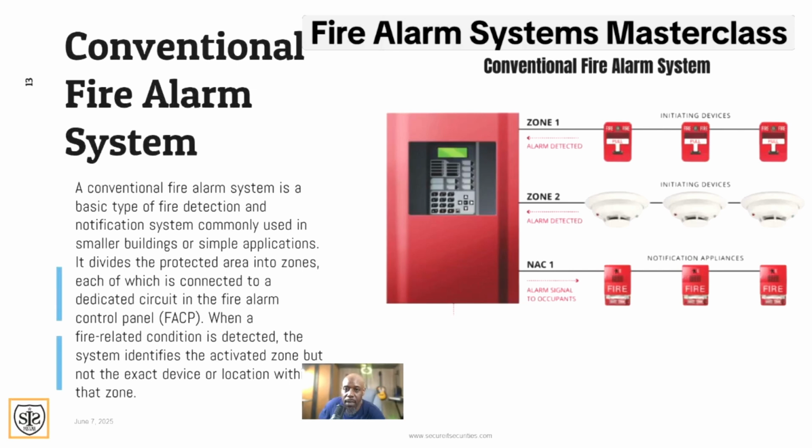When these devices go short, because that's all it's really doing, like a light switch turning on and off, once this goes into alarm, then this output will turn these horns and strobes on. There's no laptop programming really involved with this, except to set up the central station and send the signals to the center. Just put the labels on the zones and match the zones with the outputs, and pretty much that's it.